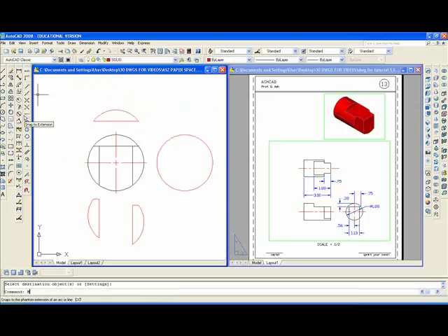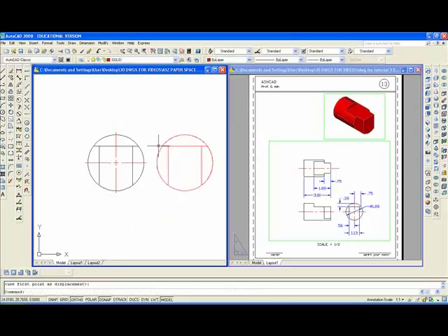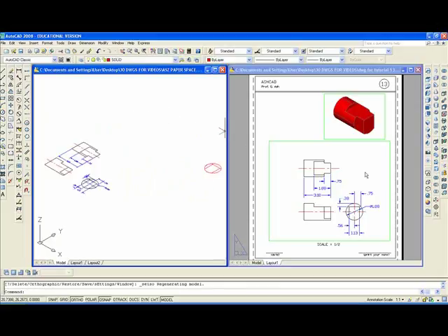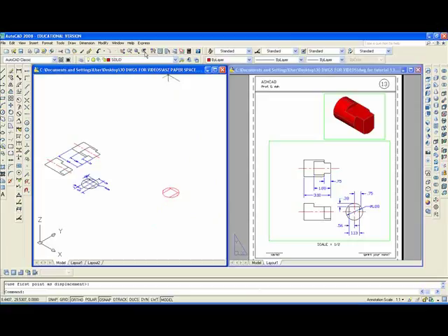And I'm going to move this segment from the quad, which is here, to the quad, which is there. And I'm going to move this one here, from this intersection here to that intersection. And I'm going to move this from this intersection to that intersection, and I'll erase this business in here. Now I'm in a position to move into southeast isometric, but I'm way off base, so I'm going to move the solid portion a little closer, like that, then zoom with the window.